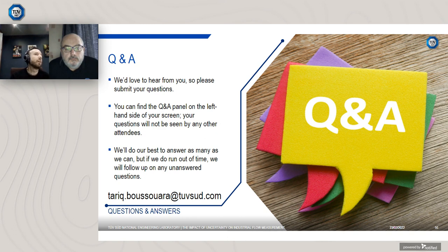One thing we have done, we test a lot of material coupons, and sometimes people will install little material coupons as sacrificial items that can be removed and periodically checked to determine how much material is actually being lost. And if you can get access to the device, visual inspection's quite good.